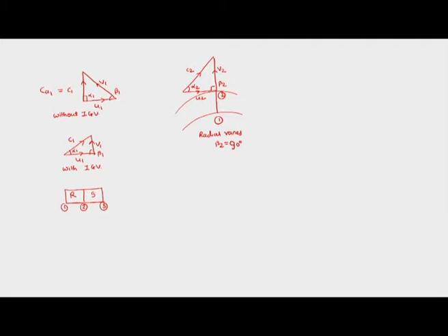But in the other case, if we have the vanes to be non-radial, where they are backward faced, then first we have this as U2. We have to remember that U2 is parallel to the arc of the circle we are drawing, and then this is V2, and then this turns out to be C2.